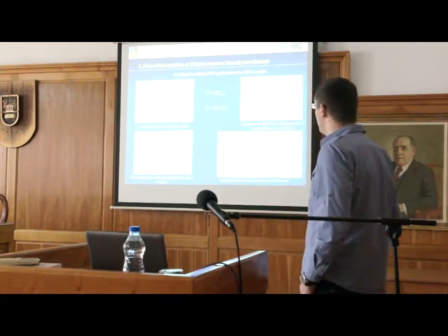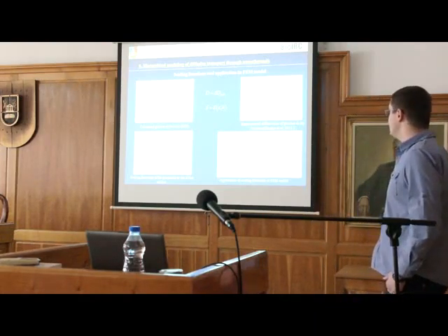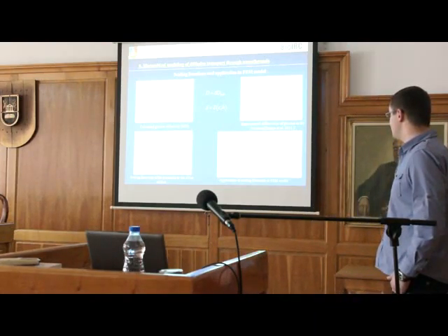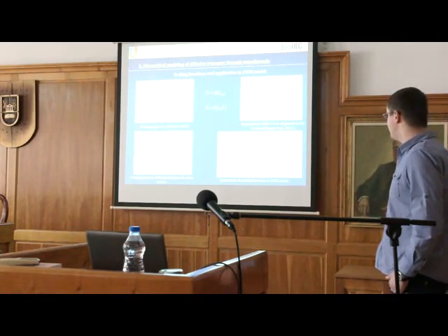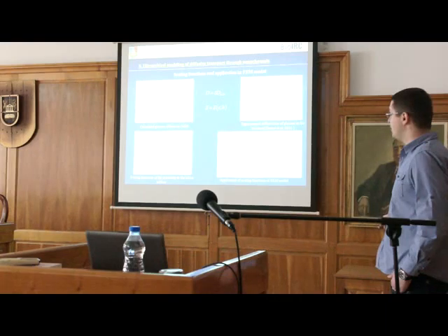and we have the dependence of diffusivity on the concentration. And how we use it in our FEM model: for example, we have some FEM domain, we have a wall, and we have some point P, which is at distance h from the wall. For this point P, we first find the concentration from the previous time step. Using this diagram, which is also here, we can calculate the bulk diffusion coefficient, D of C, for that concentration. So that is our D bulk.